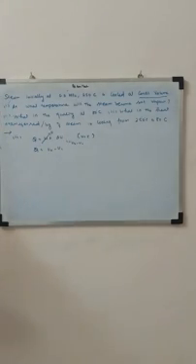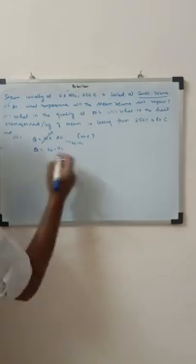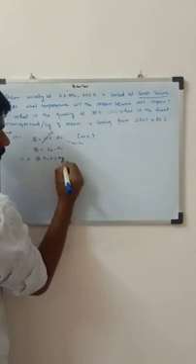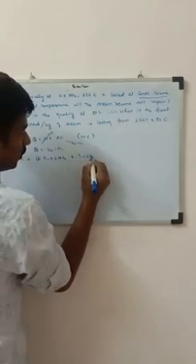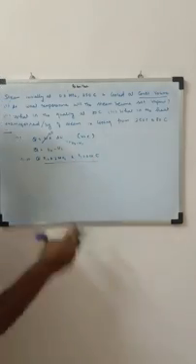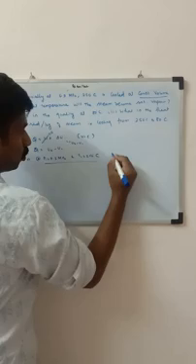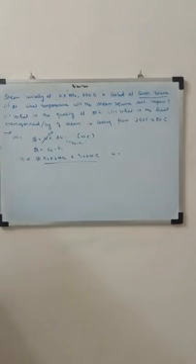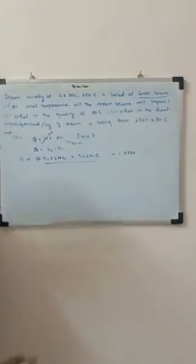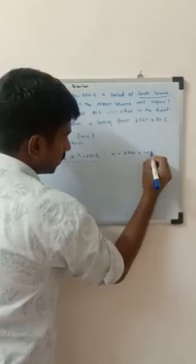So what is the value of U2? U2 is the final state and U1 is the initial state. And what we have to do? We have to calculate. So U1 is nothing but at P1 is equal to 0.3 megapascal and T1 is equal to 250. This is my first state. So I go to the steam table because this is in the superheated region. I go to the superheated steam table, and for this value, the U value at this point is equal to 2729.0 kilojoules per kg.